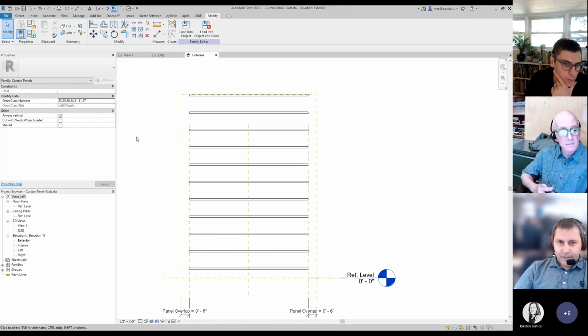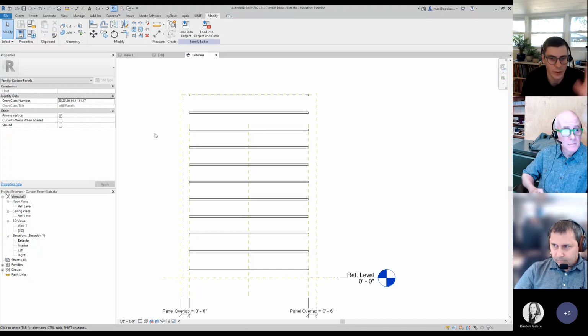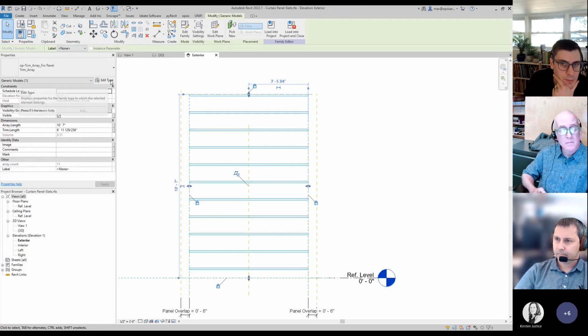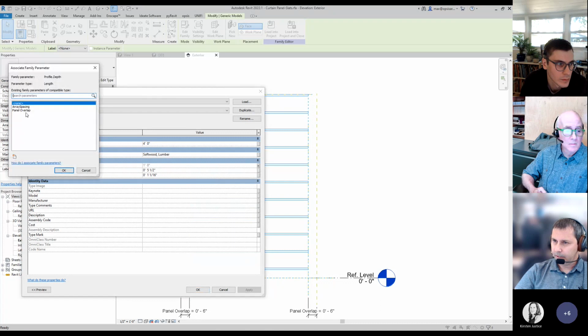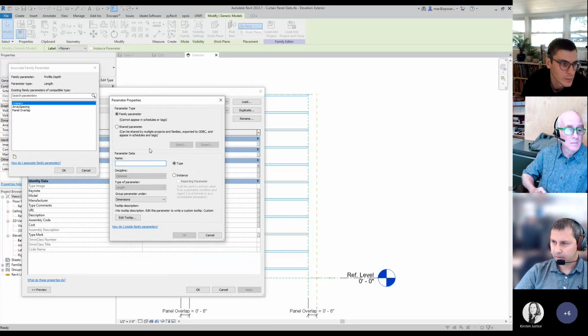And it might be clear for everyone, but the parameter used to link to the other one was the same type of parameter, so a dimensional one for a dimensional one and so on. Yeah, and when you're in here and you want to link a parameter to an associated family parameter and you create one, it usually gives you the correct parameter type. For this one, it's all grayed out as far as the type, so that it's the same thing. Exactly.